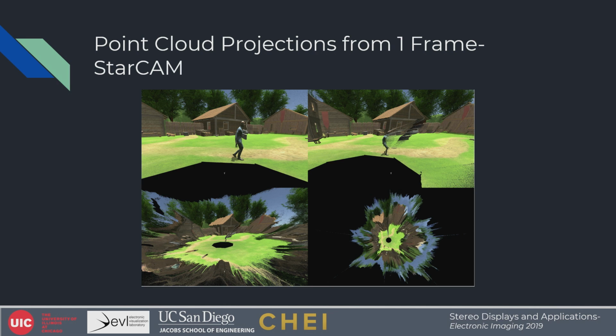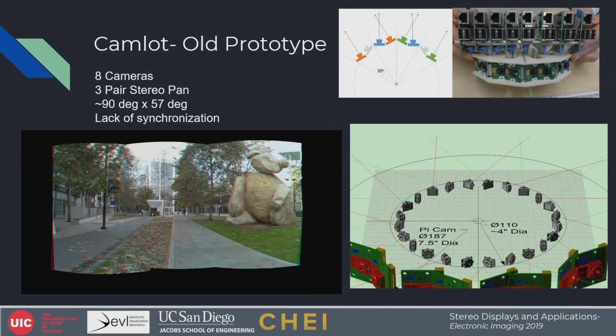And as you can see, the point cloud from a top-down view of this world is not very great, but when you look at it from the perspective of the camera, it actually works out to be pretty great. So really thinking about how we can do pretty decent depth estimate from the perspective of the camera, but not great of the whole environment. Moving the camera around and applying multi-view geometry techniques would result in much better results.